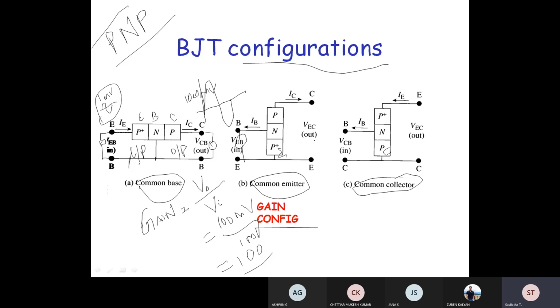The gain may also vary depending upon the parameters being used, such as the resistor. Design of electronic circuits will be based upon the specifications. We will get the output voltage, and the gain can be calculated accordingly. Here, if the output voltage is 110 millivolts, 110 divided by 1 millivolt, the gain is 110.